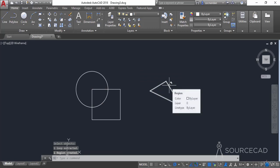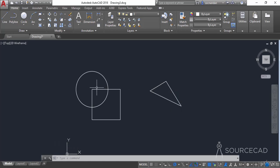Now when I move my cursor, you can see that we have a region here as seen on the tooltip, and the complete geometry will be selected. So in all of these three cases, we had completely closed geometry. That's why I was able to convert them into region, and that's one of the conditions which needs to be fulfilled for converting an object into a region. Okay, so now we have the regions.